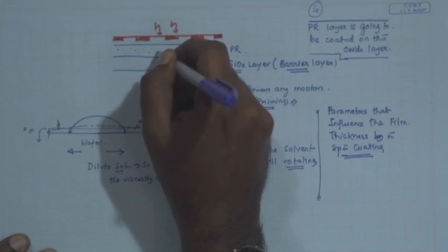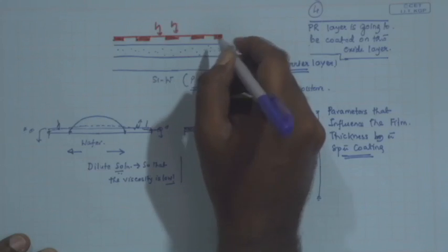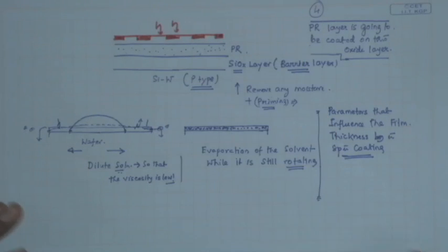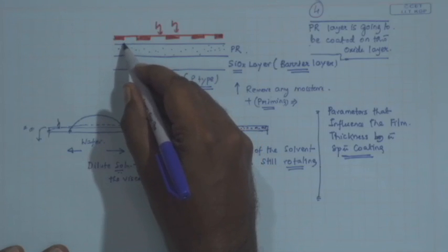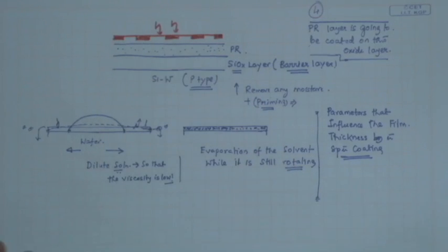But if the photoresist film contains solvent, the solvent does not change property irrespective of whether it is in the zone exposed to UV light or not. Therefore, even after exposure, there will be significant smearing, because the solvent does not respond to the UV exposure, only the photoresist does.